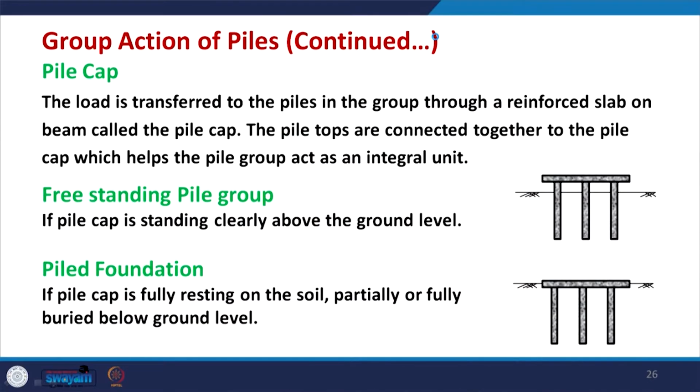Continuing with group action of piles, when you have a number of piles, they are connected through a slab called the pile cap. The pile cap connects all the heads of the piles, and the load is transferred to the piles in the group through this reinforced slab, or slab on beam, called the pile cap. The pile tops are connected together to the pile cap, which helps the pile group act as an integral unit.